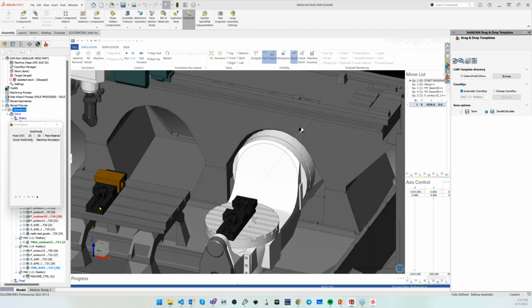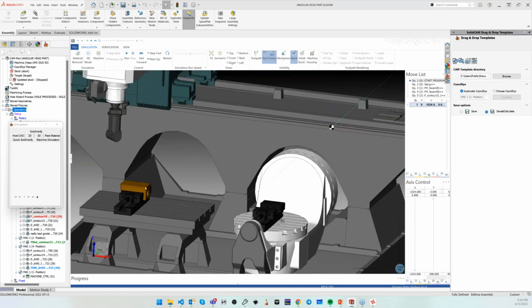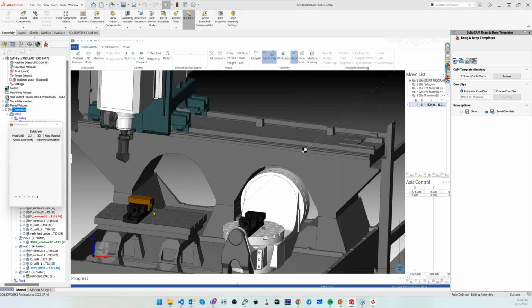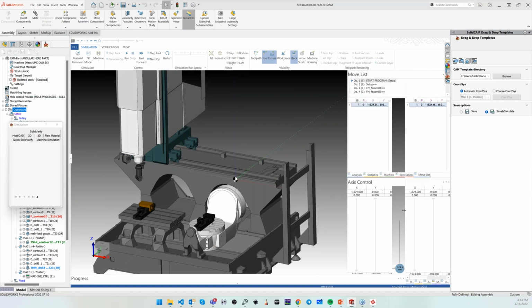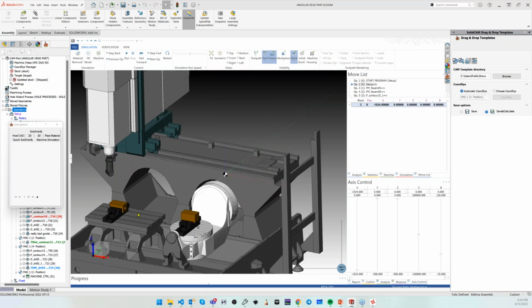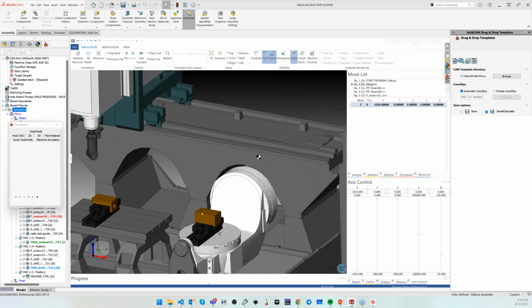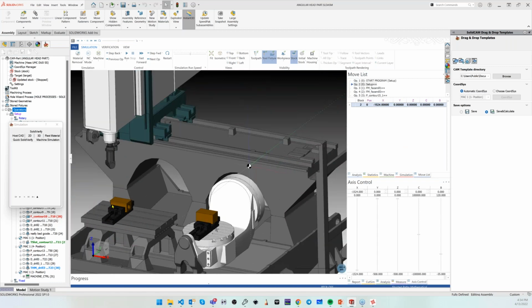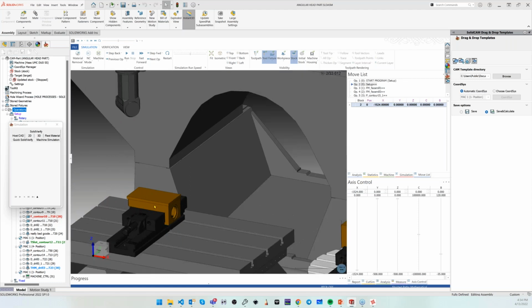It has two tables. The first table is static. Generally we use it to prepare parts, like for fixtures, and finish the parts. And the second table has a 5-axis rotary table. So I can mount my stock here, make all my jobs here and finish my part. Then I make the last operation on the second vise.